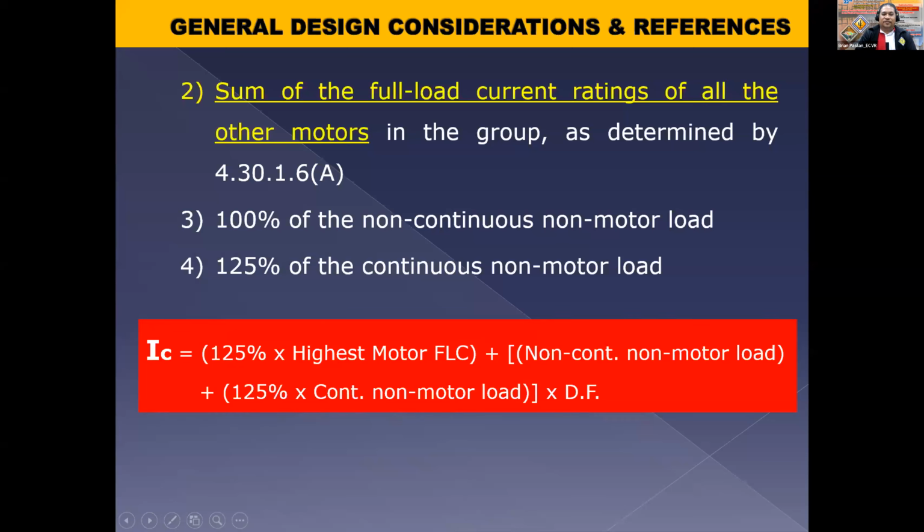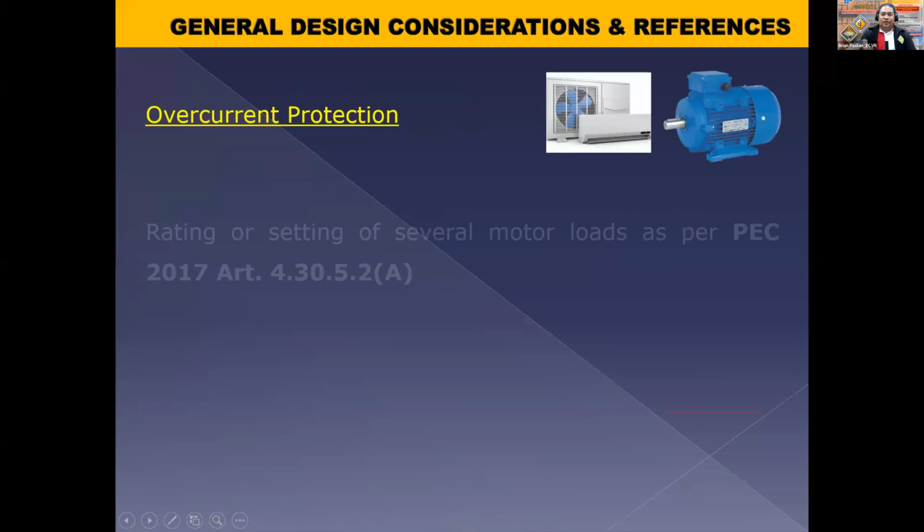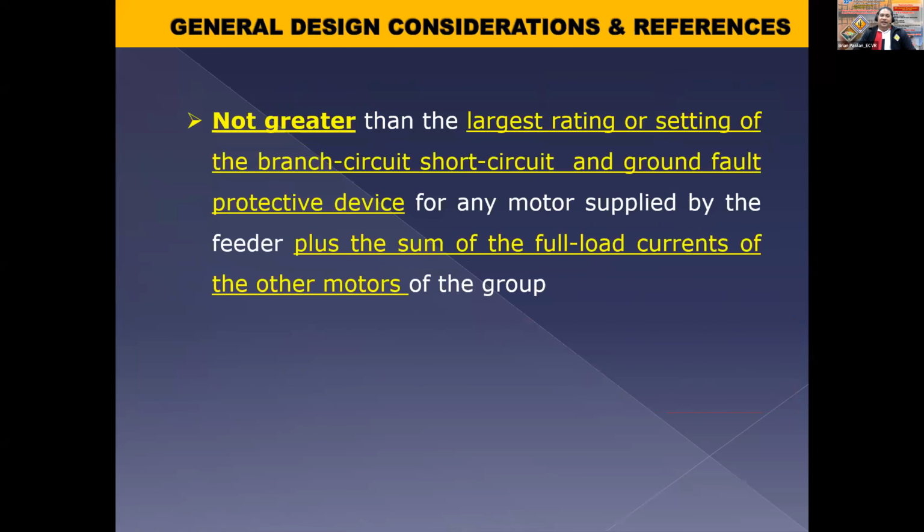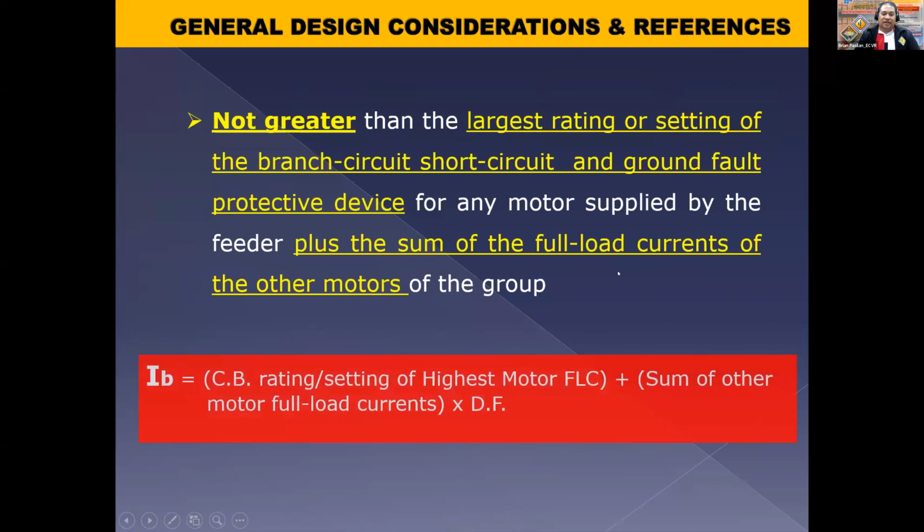So for motor protection, ito yung kaibahan, no? Now, for combination of motors, no, for feeders, ang circuit breaker natin for feeder circuit breaker, ang first consideration na is no longer the amperes but the rating or setting na of the protective device, no? Then plus the sum of the full load currents.